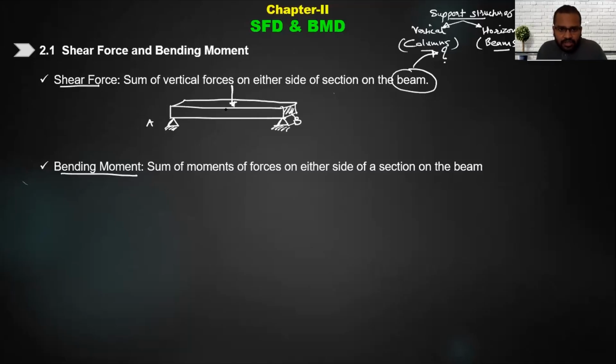Because if I take an imaginary cross section here, then for this cross section this force is a tangential force, right? Tangential force on this cross section. It is perpendicular to the length of the beam, but it is tangential to the cross section, and that tangential force is also known as the shear force.